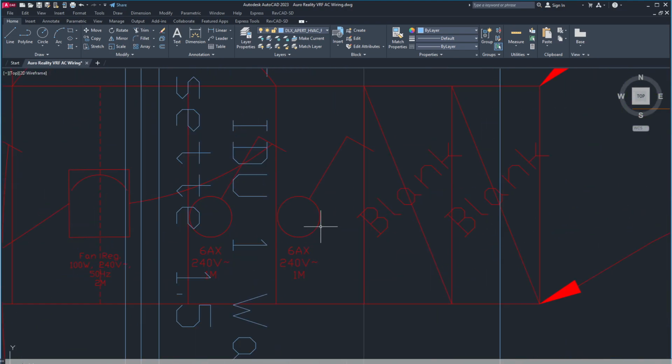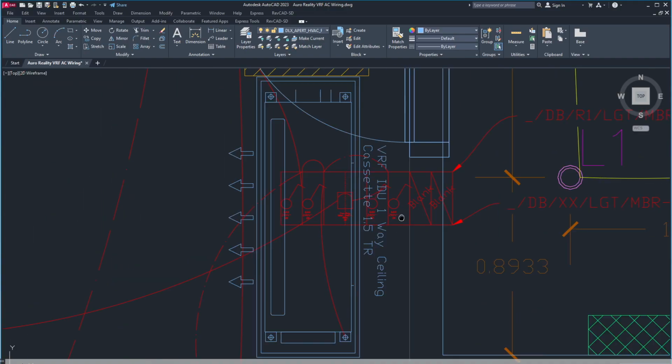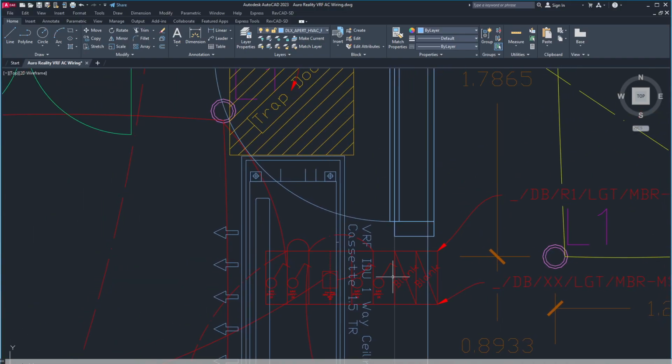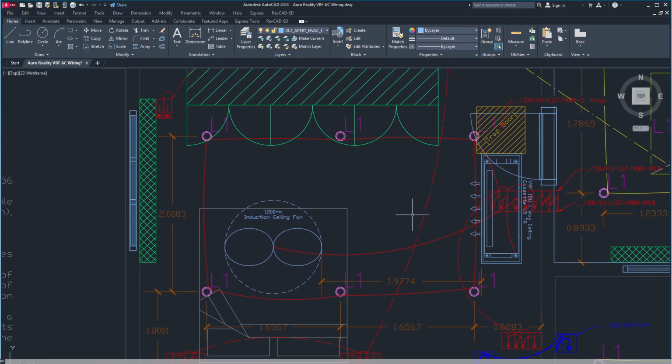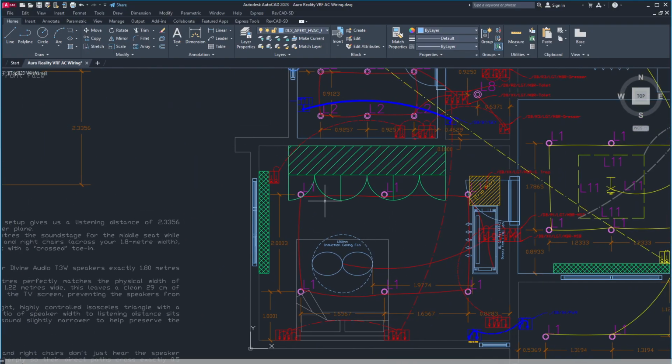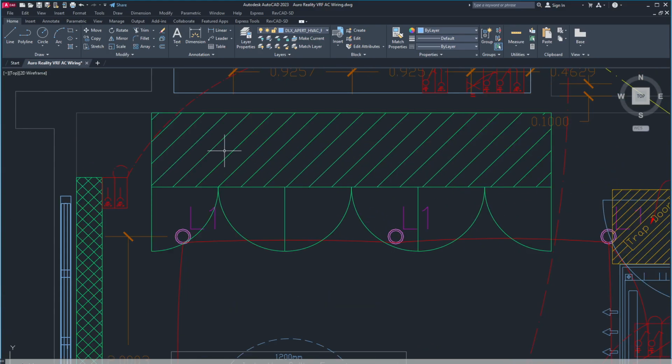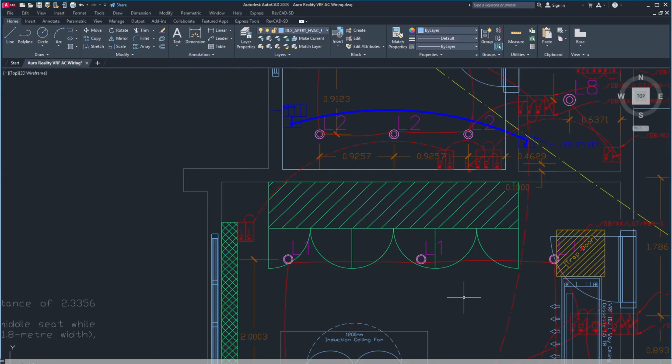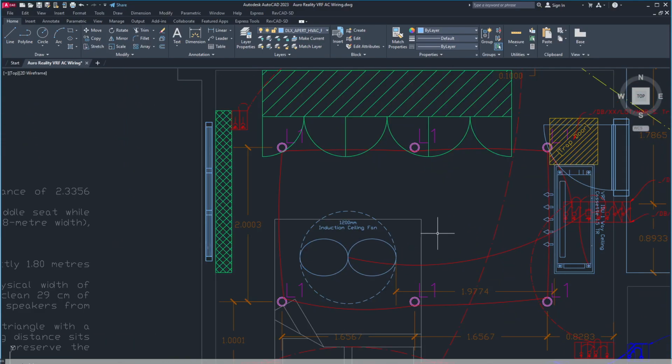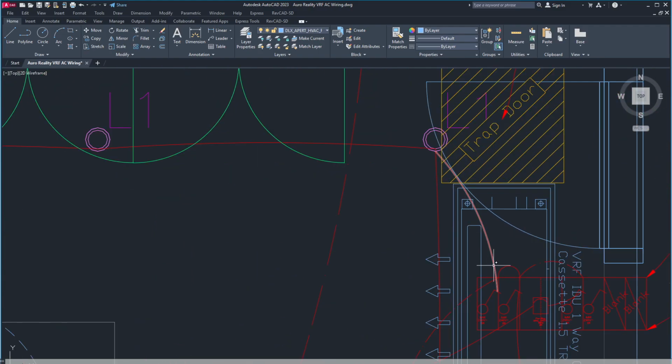Then this switch I have given as a spare, and this one I have given as a blank. Down the line, nowadays, people are going for a lot of curves and design profile lights. They might place a profile in this cabin, under-cabinet lighting and all that. So for that, scalability has to be there.